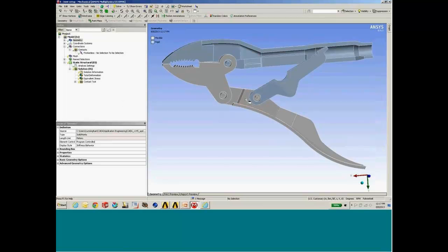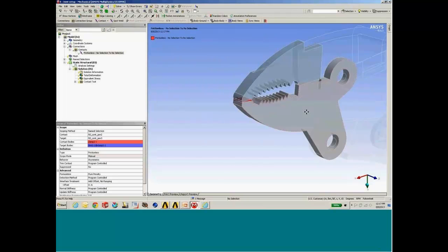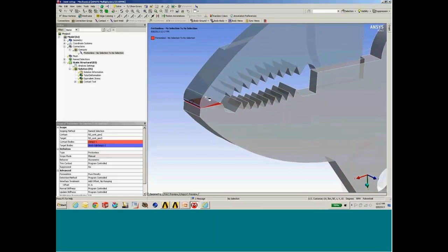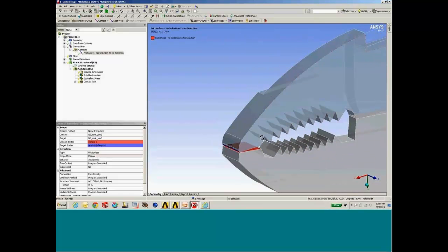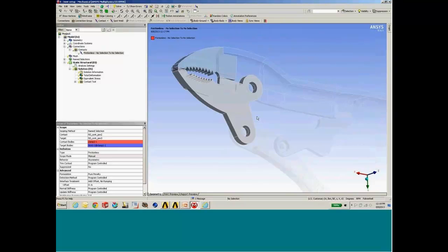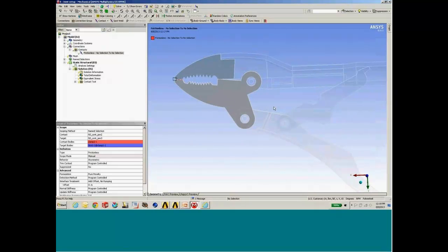These lower two bodies will be meshed with finite elements. We can use a surface-to-surface contact region between that flexible body and the rigid body. The rigid body in this case would be the target surface for that contact region. So that's possible between flexible and rigid bodies to do the nonlinear contact.